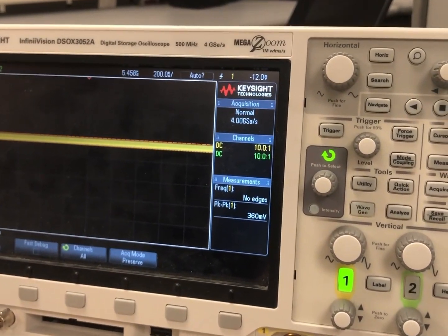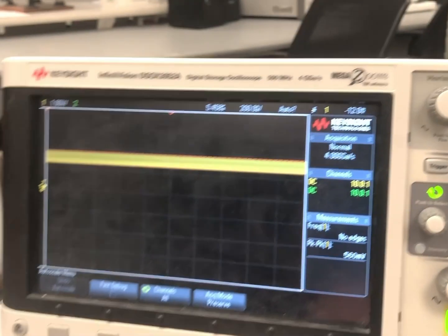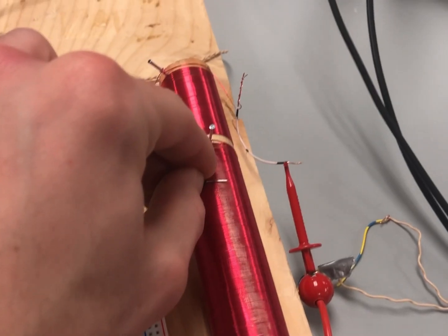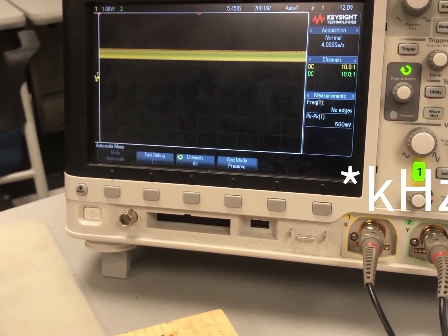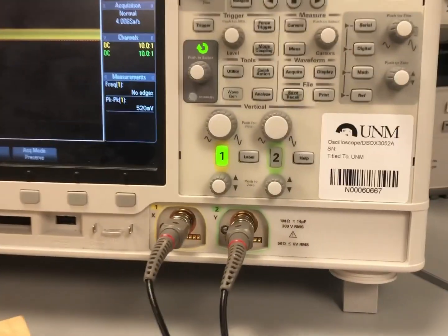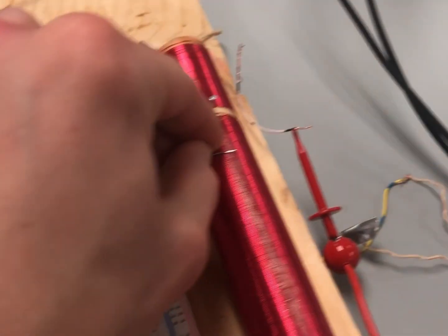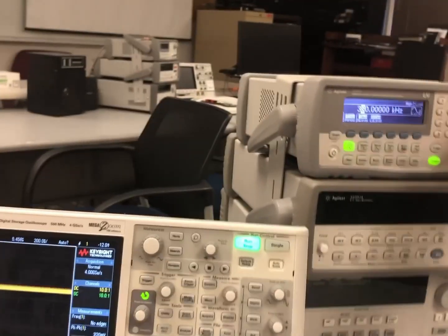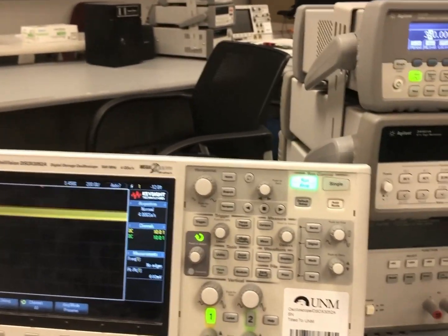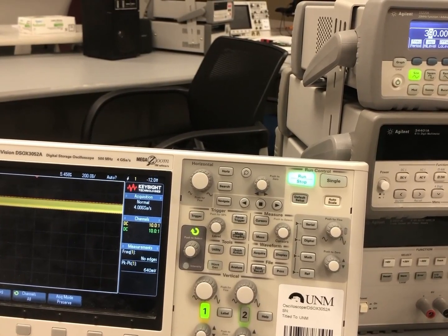I'm not sure. I can try to adjust this to have it peak again. So our new resonant frequency after we're doing this is around 380 megahertz. The amplitude isn't quite as good as the last ones, but that's kind of typical for these bandpass filters. And when I take this off, go back to that, I can readjust it back to peaking at 390.